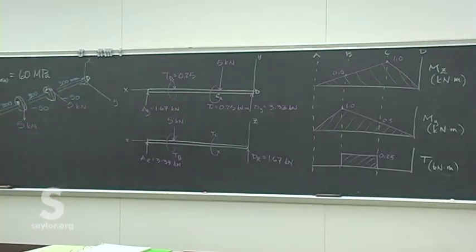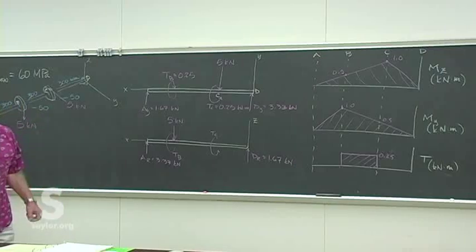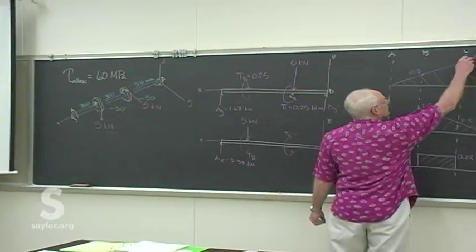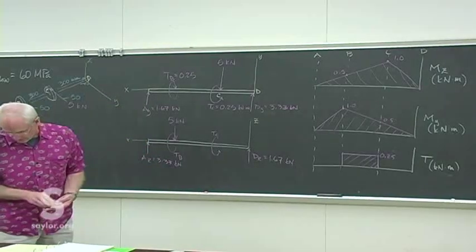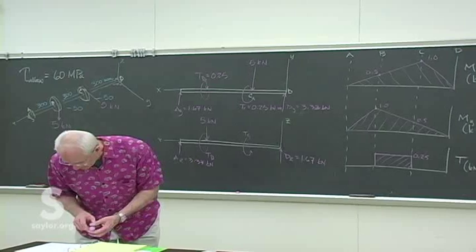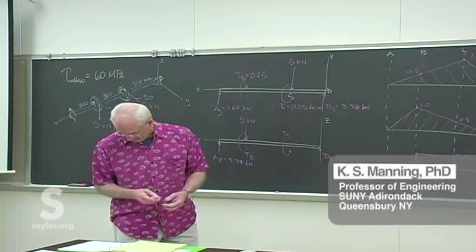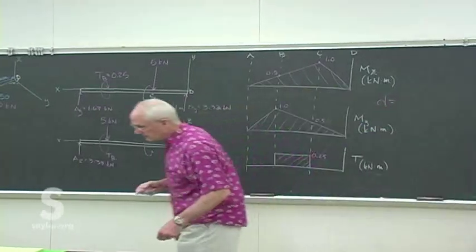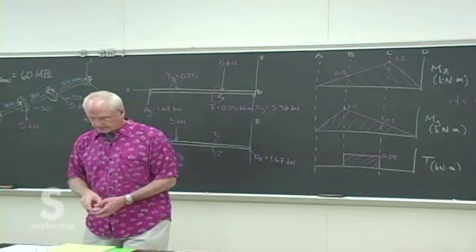Two far ends are free to turn. So you really only need to do one place, do the symmetry of the problem, the 1 and a 0.5 and a 0.25, because you get the same thing at the other gear, you're going to get exactly the same values. And so then you can finish that bit. And you should get a diameter, then we're right at the end. Diameter of, you round it up to the nearest millimeter probably, 46 millimeters. So we're at the end there.